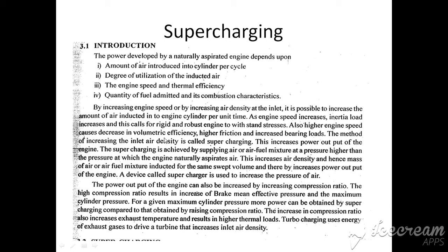The method of increasing the air inlet density is called supercharging. So, supercharging is a method of increasing the inlet air density. This increases power output of the engine. Supercharging is achieved by supplying air or air fuel mixture at a pressure higher than the pressure at which the engine naturally aspirates air.